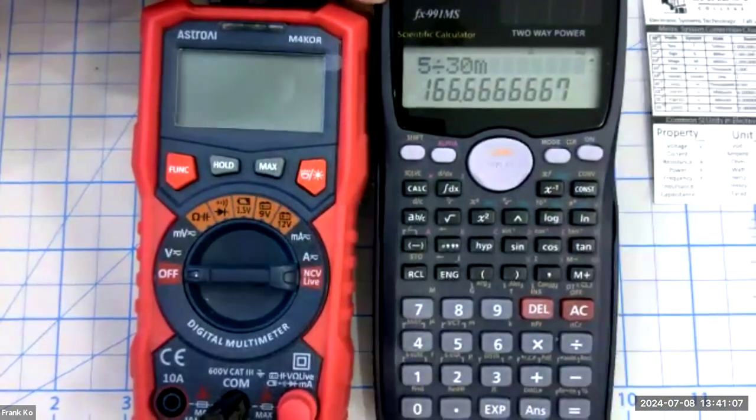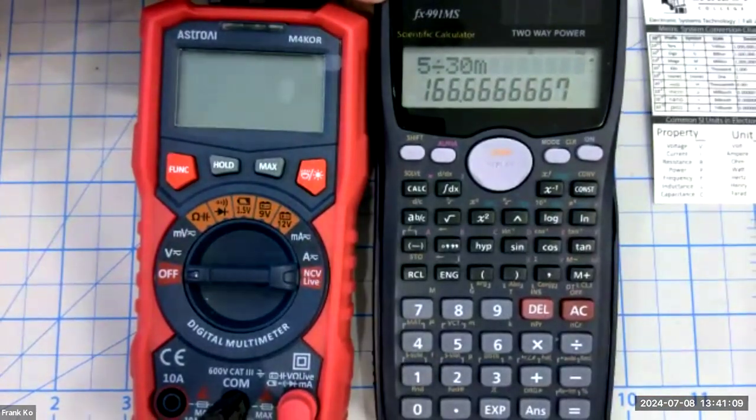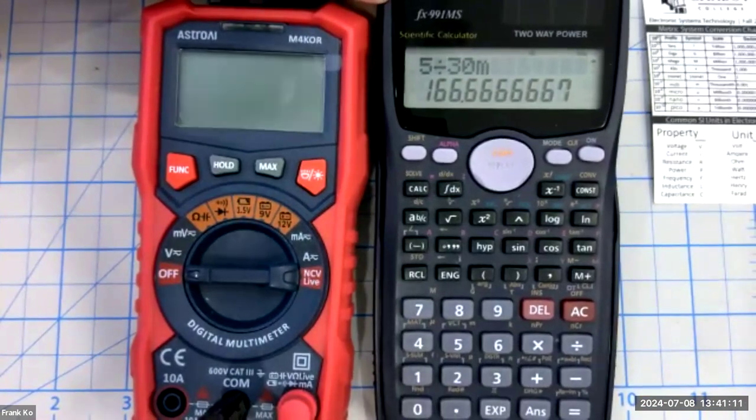We'll enter a new device called a potentiometer, something that we can dial in, a variable resistor that we can tune to be very close to this number in order for us to achieve 30 milliamps. Now, let me show you how that's done.